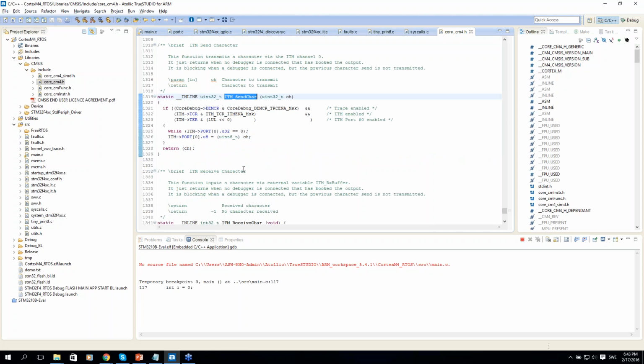What if I'm using an i.MX part? Can I do the serial wire viewer with that? No, you can't. Freescale or NXP i.MX is a Cortex-A application processor. I doubt they implement serial wire viewer. I think it's only available in Cortex M3, M4, and M7. Cortex M0, or M0 Plus or both, I'm not sure, has another type of tracing. So this is only for M3, M4, and M7.